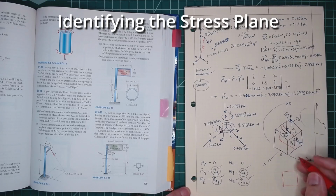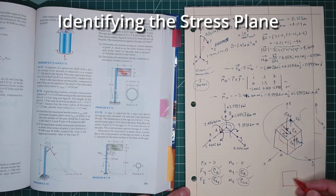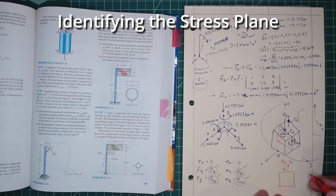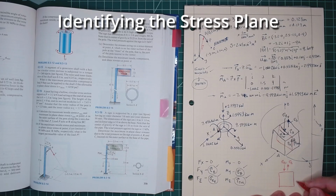Now if we take a look at this, we can draw this in a planar sense and show all of these forces on here again. So we have our sigma ZF going in compression. We have our sigma B acting in tension, and then we have our shear stresses on here. Maybe I'll draw the shear stresses on this face just to make it a little bit easier, so we have our tau B and our tau due to our torque on there.